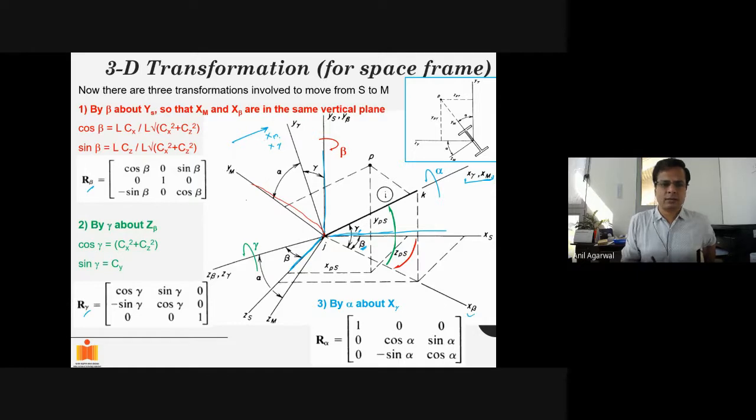Then what will be the y and z axes of the two? So let's say xm and x gamma. Let me draw m with a different color. Let's say the member coordinate system is also aligning with this one. So that is xm, in red. Probably it has these two axes, y and z. So this might be ym and this might be zm, and it has to follow the right hand rule. So x to y, you turn your fingers that way, and z is perpendicular to that direction. Fine. And then the other coordinate system is x gamma, and the corresponding y gamma and z gamma will be here.